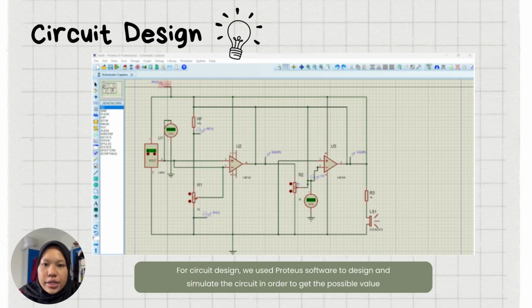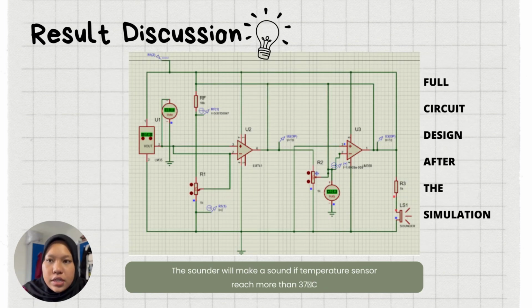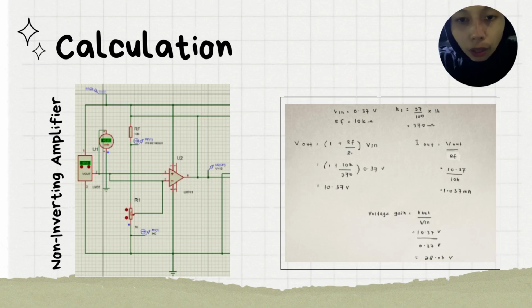Next, for the circuit design, we use Proteus software to design and simulate the circuit in order to get the possible values during the simulation. For the result discussion, the sounder will make sound if the temperature sensor reaches more than 37 degrees Celsius. I will explain the calculation part, which is for the non-inverting amplifier circuit.